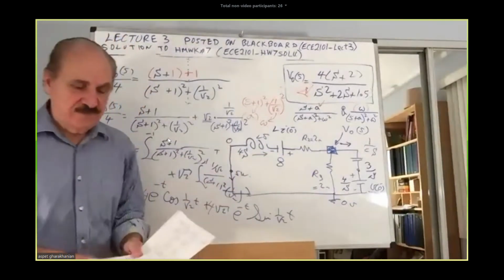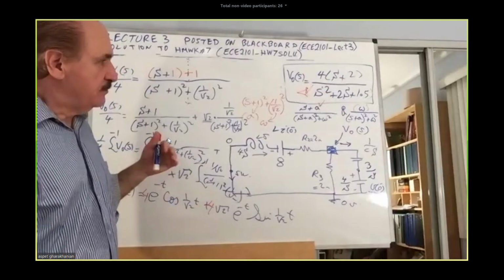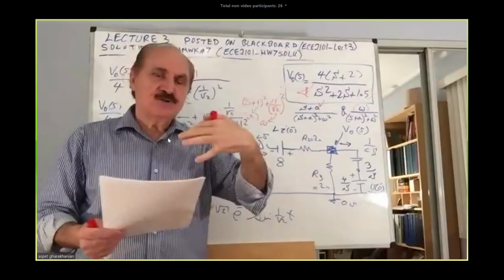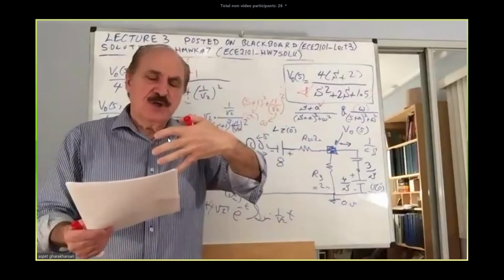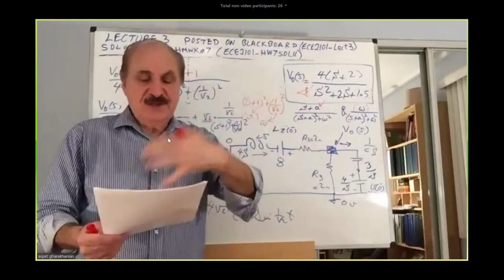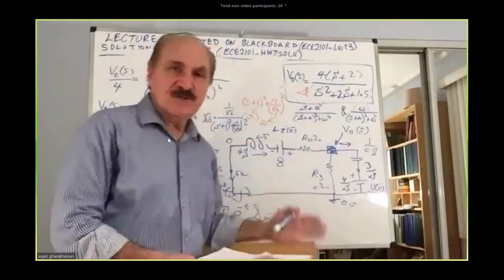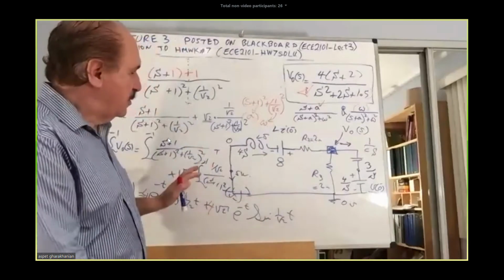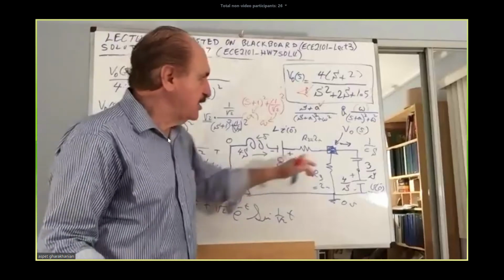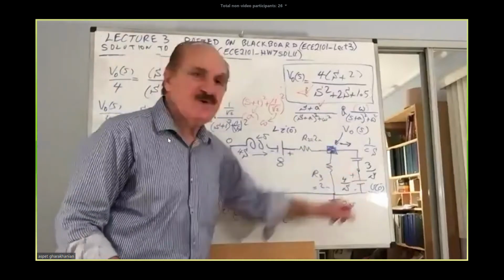So I demonstrated for you, with that example, how you can utilize the initial condition in a maybe practical circuit, by throwing the switch, you can carry over that initial condition into the models for your capacitor and inductor in the Laplace domain, build the circuit, apply nodal analysis as if you're doing nodal analysis for DC, except you're utilizing Laplace impedances and some constants within the circuit.